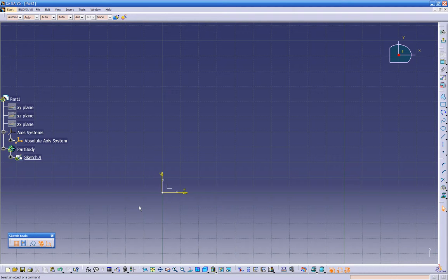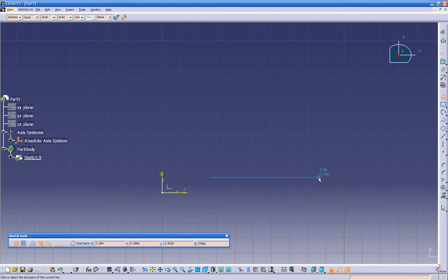Let's create another sketch. So let's try this new option right here, the profile. So let's click on it and let's create. See, when you create a straight line, it becomes blue. So let's go straight over here. Once you go up, then if you hold and drag it, it's going to create a circle. So let's create a circle over here.